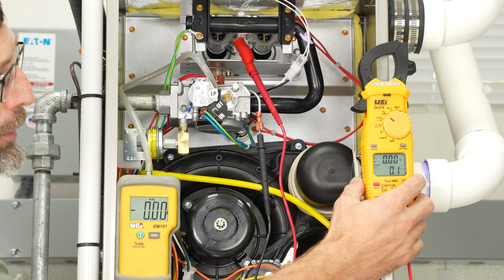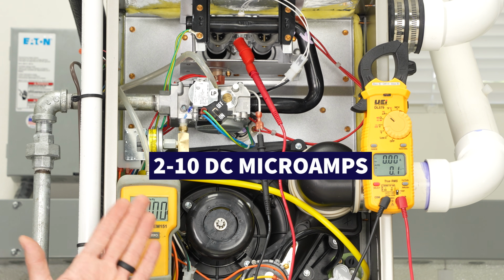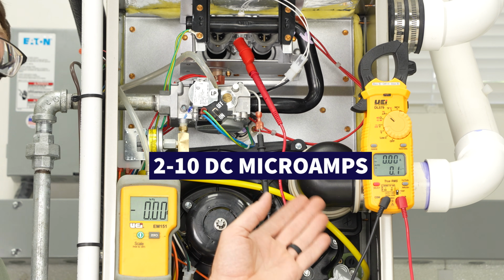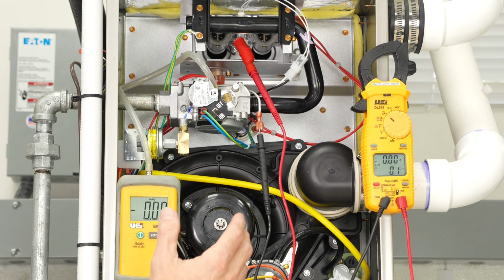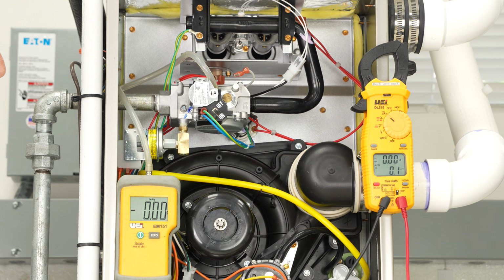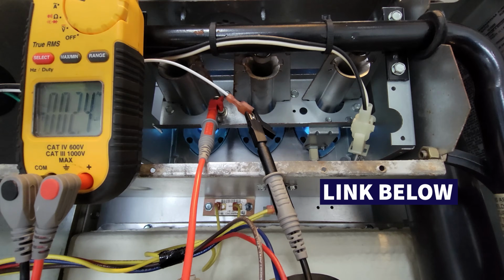But you want to have a good DC microamp signal, and so we measured about 4, and basically anywhere from say 2 to 10. Really, you want to be closer to say 3 or 4, and so that is a good signal. But if you were lower than say 1, you know you have a problem. It could be with the ground wire, or it could be with the flame rod or the flame itself. And basically, it's converting an alternating current signal on this wire into a direct current signal that's measured on the ground frame of the furnace, and it's measured at the circuit board down here. But if you want to learn more about that, make sure to check out the other video we have on flame rectification in the description section below.